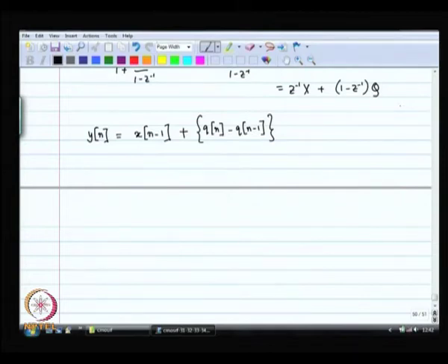So, that is what your output series is going to look like, a series of numbers. If you want to plot the spectra of these, please go ahead, you will find that z inverse x is actually an all pass transfer function, it passes everything, it is just the previous sample of x, right, and 1 minus z inverse is a high pass function. If there is a change in quantization noise, then it is going to go through. If there is no change, it will not go through.